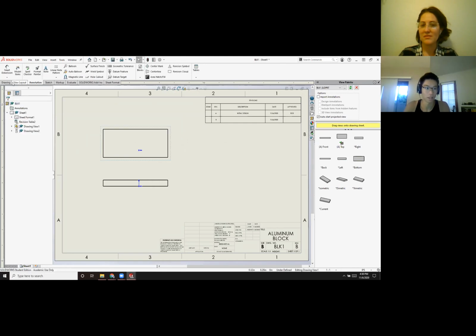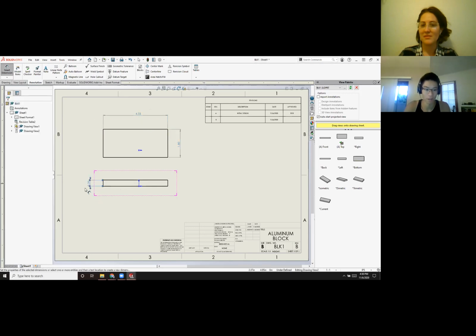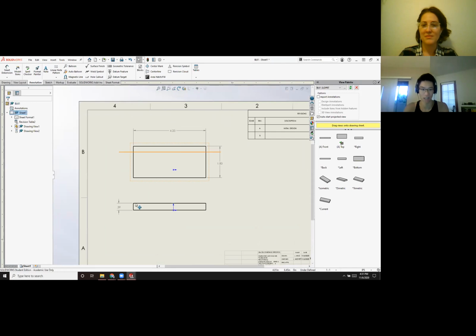And to make this simple, I'm just going to go ahead and throw a few dimensions on it. Y'all remember how to do dimensions and all that. Oh, this is in inches apparently. That's fine, whatever. Oh, it's in ISO drafting standard right now. I'm going to switch to ANSI drafting standard. Don't worry about that. That's mostly just dealing with what kind of drafting you use. Most people use ANSI drafting standards, and it changes how things are listed out.